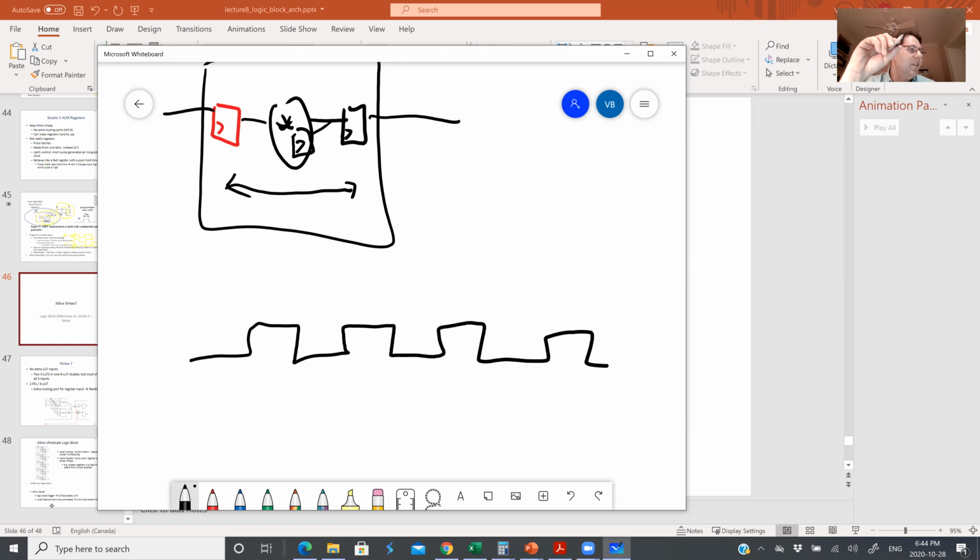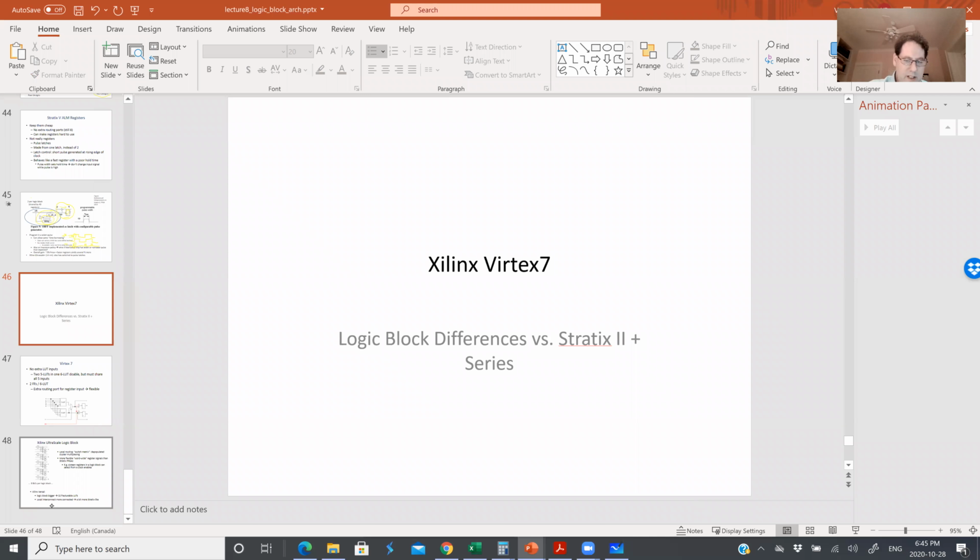Yeah, Camilo, you're asking about if you use these pulse latches and time borrowing, you'll have to worry more about hold time violations, and that's true. The CAD flow does get harder. The tools analyze for the hold time violations. The reason pulse latches have become popular in FPGA architectures is they do present this trade-off: because there's only one latch instead of two, basically the sum of T setup plus T clock to out, basically the delay to get through the register, that's basically the delay before the clock edge and the delay after the clock edge. The sum of those two things is essentially the delay through the register. That gets smaller.